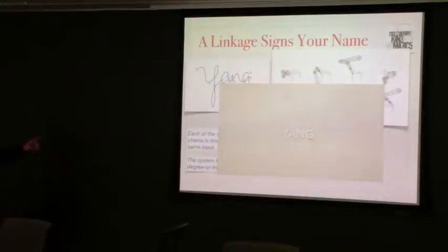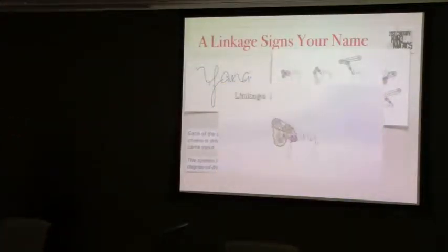What we did is, you can see we have 8 Bezier segments. Each has a linkage that consists of 6 links. The result is that an nth degree Bezier curve has a 2n linkage that draws it exactly. What we can do, however, is simplify those Bezier curves and draw them with links that only have 2 joints.